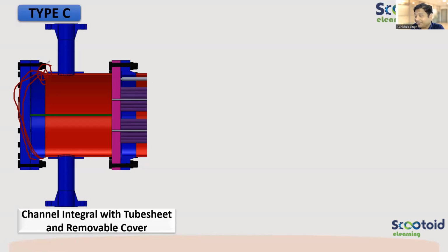If I'm having a cover, yeah, you're absolutely right with saying no, but yes, Weber, to the point. Now, if I make this also integral, how will I access this? I'll not have any access, right? I cannot access this face of the tube sheet to clean it. This side anyway is not accessible because of the tube bundle. So I'll not be able to clean, so maintenance will not be possible. So that is the limitation if we have that.